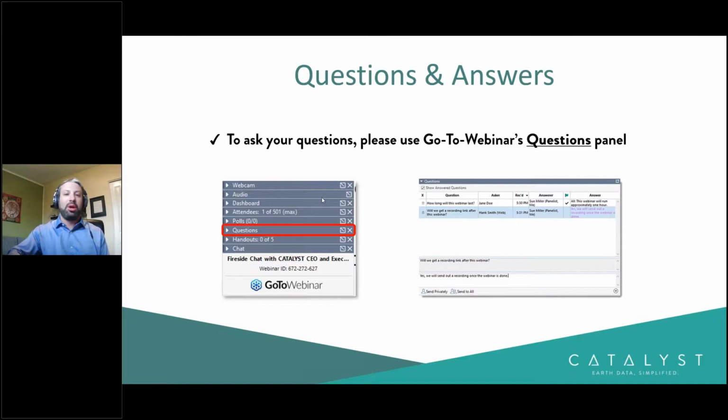That's a great question. So ortho-imagery is actually a short form. The long form of it is ortho-rectified imagery, and this is really just performing a geometric correction of the imagery to transform it. So it's a photogrammetric approach to transforming the imagery or morphing the imagery based on a particular model using reference information to correct it so that the pixels on the image are accurate, or the features on the image have coordinates that are accurate with those features on the ground.